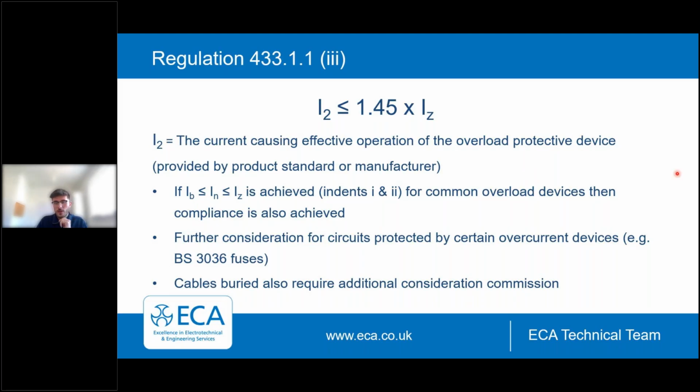The factor 1.45 is based on a combination of experience and investigation. This has shown that the types of cables that are considered within BS 7671 can safely withstand a small but undefined number of periods at excess temperatures corresponding to currents not greater than 1.45 times their current carrying capacity.